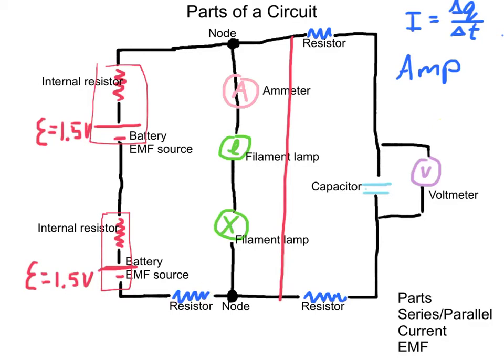If this resistor wasn't here, we'd be in big trouble. At that point in time, because there's nothing to slow the current down, so to speak, no resistor to fight it, the current would skyrocket. It would grow, in mathematical senses, up towards infinity. In reality, it can't get that far. You have an internal resistance in your EMF source that would eventually stop it. But whenever you have that much current going through your wires, now your wires actually get really hot. They begin to act like resistors. Your wires get really hot, and that's what causes house fires with a short circuit.